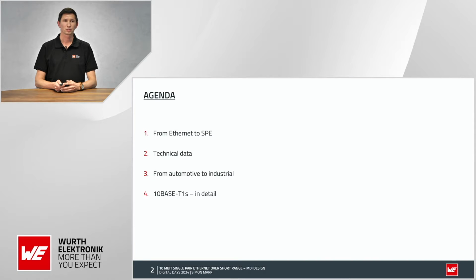Today we want to go over 4 different topics, starting from Ethernet to SPE, then looking at the technical data, then from automotive to industrial, and at the end looking at 10BASE-T1S in detail to know what we have to define or design during the process.